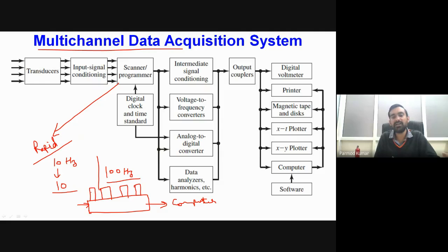For example, if I want to measure a pressure and the output of the pressure transducer is current, then obviously I'll employ a current module, and that will connect my different pressure transducers, and depending upon the value of current, after post processing we will get the corresponding value of the pressure. Then on the same generalized system we may employ another module for temperature, which will acquire the voltage output. Then it will have some conditioning circuit which will convert the voltage signal into the corresponding temperature value. Similarly, we may have systems for measurement of the flow rate and other properties as well.